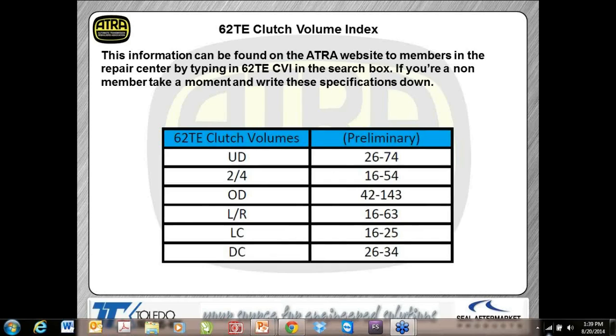So, to me, like any lip seal, if this was an aluminum piston or a steel piston that had a lip seal on it, obviously I'd want to change it during rebuild. So I feel the same way about molded pistons. It's just another lip seal that should be changed during rebuild.